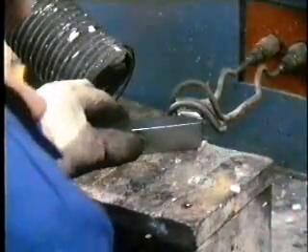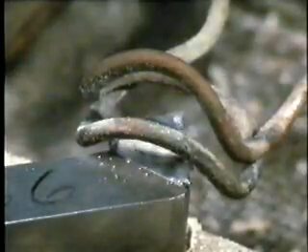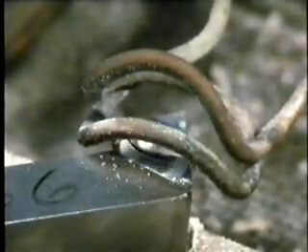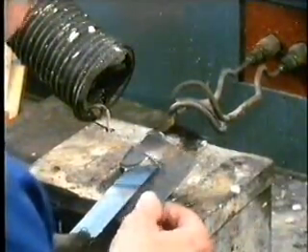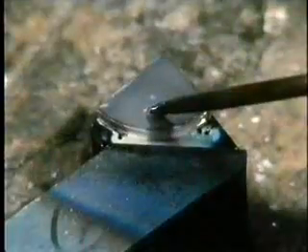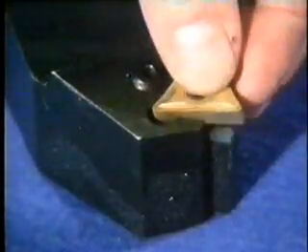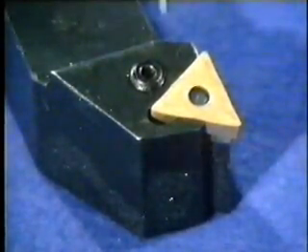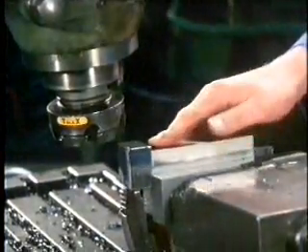In the beginning, because of the expense of the process, the cemented carbide tips were brazed onto the tool body. This only added to the cost, because when the tip wore down, it had to be reground painstakingly using a silicon carbide wheel. And after all that, the tool had to be reset. Nowadays, to save time and money, specially prepared inserts and holders are used. Holders are made from toughened steel, which first undergoes a series of milling operations.